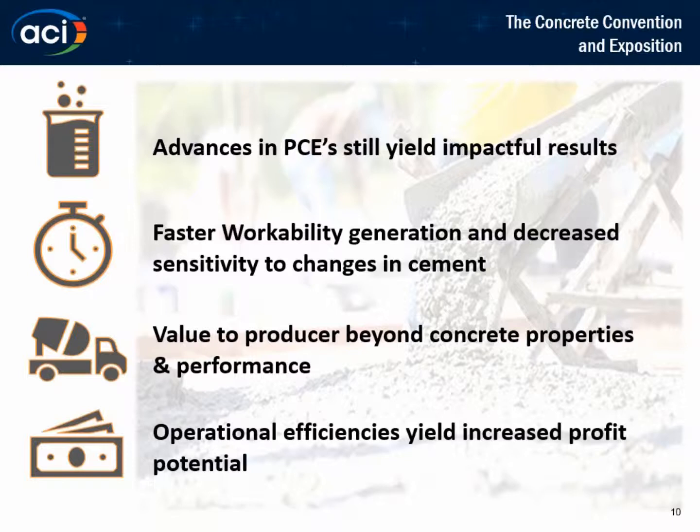Question over here. Have you checked if your new PCE is sensitive to the presence of clay in the concrete? Is it sensitive to clay is the question. So it's sensitive to clay like the rest of the PCE families are. Clay in particular, your swelling clays, it will still be impacted by the presence of a swelling clay, no more or no less than a traditional PCE.